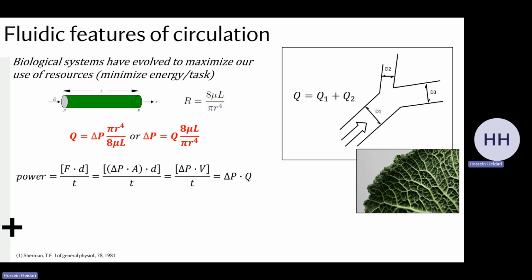And the force required to push the cylinder: there's a pressure acting on this side and one pressure on the other, and the net ΔP times the surface area is how much force you need to push it, right? That's the cylinder of fluid as it travels through the blood vessel. There's a pressure before and a pressure after. If you figure out the difference, multiplied by the area, it will be the amount of force needed to push that forward.